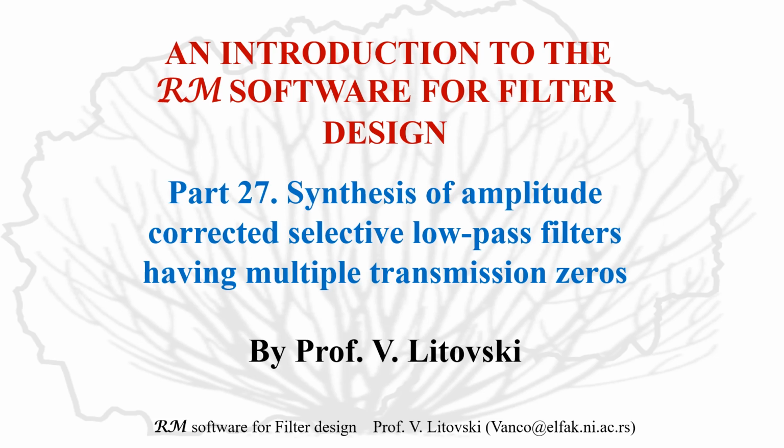That means that the existing polynomial monotonic filters will be upgraded or extended with transmission zeros in order to improve the selectivity and the passband performance.